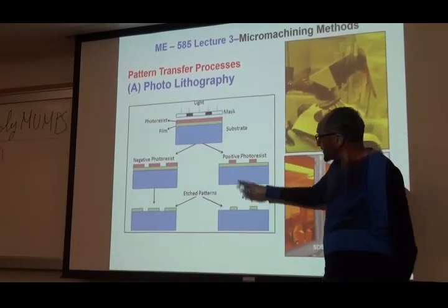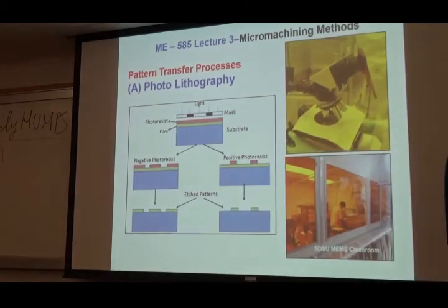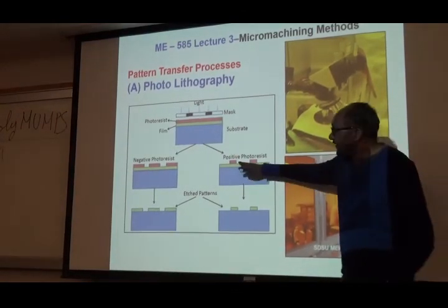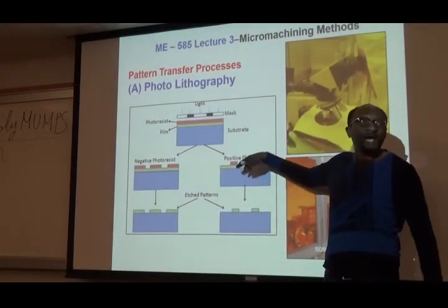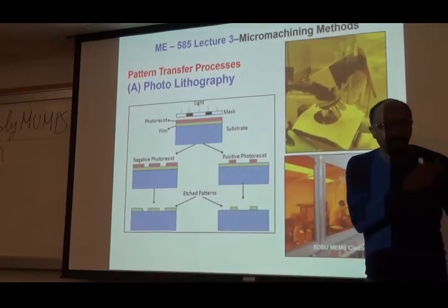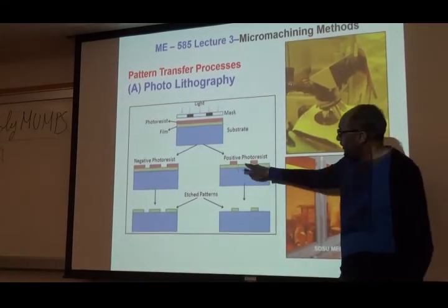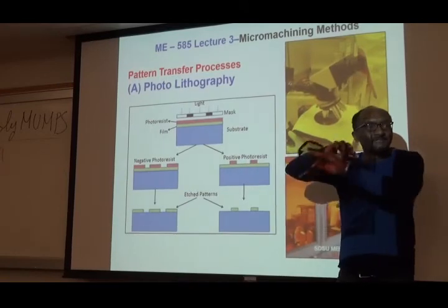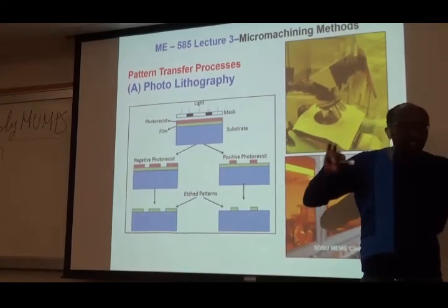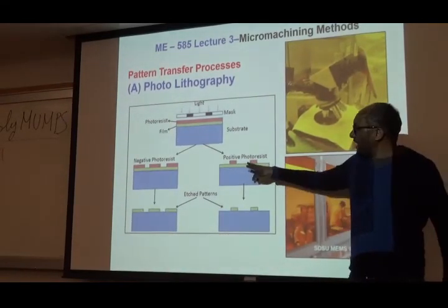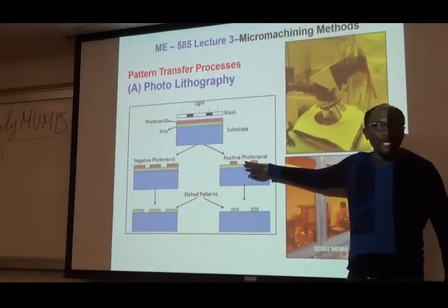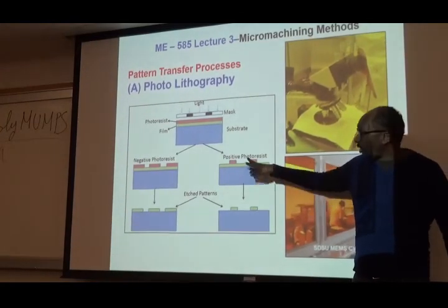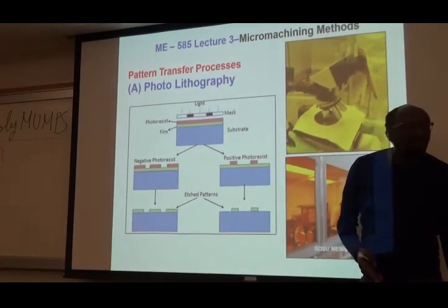But the green one, I also do something, patterning, right? So the photoresist, before I remove it, I'm going to do some kind of etching, which I'm going to cut. I'm going to explain that part. So what happens is you etch. So this guy kind of acts like protection. Then once I make the opening, I can deposit or I could etch away stuff.